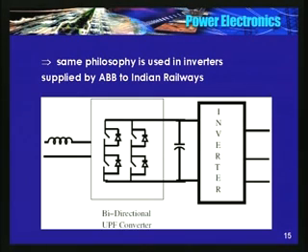Power factor is unity. By controlling the magnitude of the source current, you can maintain the capacitor voltage constant. In other words, if there is a perfect power balance of input as well as the output, capacitor voltage will remain constant, and it is possible. So you can maintain a constant DC link, power factor is unity, bidirectional power flow is possible now.